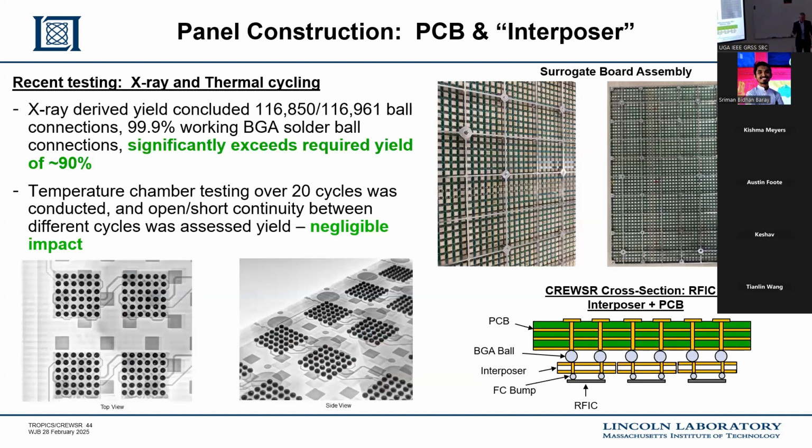Okay, so the engineering behind making that panel is extremely difficult in a number of dimensions. One thing, just the sheer attachment of those integrated circuits to the panel is really challenging. There's so many solder joints, right? So the solder joints have got to be electrically effective. They've got to be mechanically secure. They've got to be thermally effective.